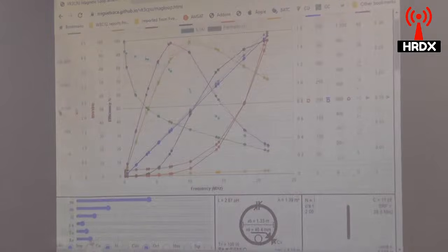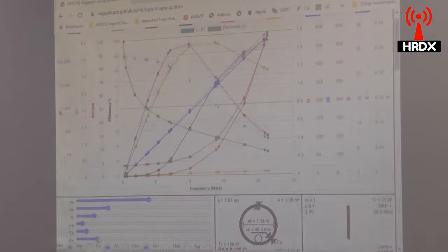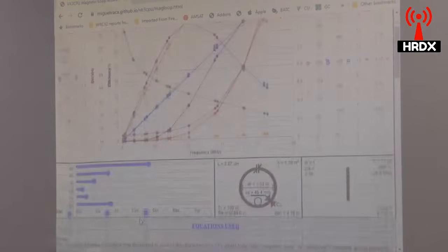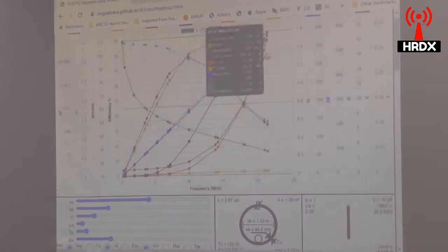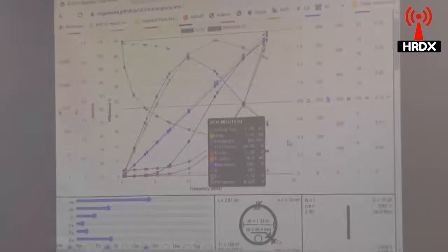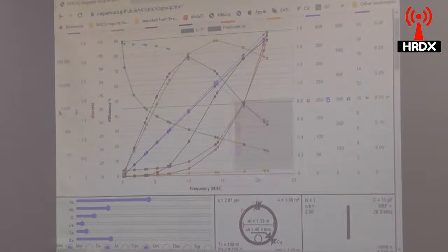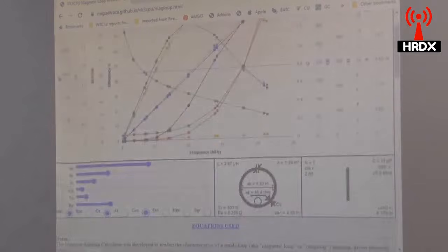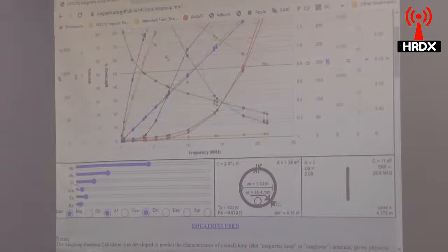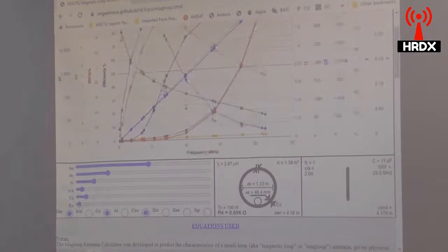I'll keep going. Let me get down to maybe 1 ohm. Now, some weird stuff happens in the middle here, but I'm down to 0.255 of an ohm. And you've dropped out, you've got an okay for 40 meters, for 80 meters, for 20 meters, but the rest of them have dropped off the scale for not much change. So it's worth doing whatever you can to get that ohmic resistance down.